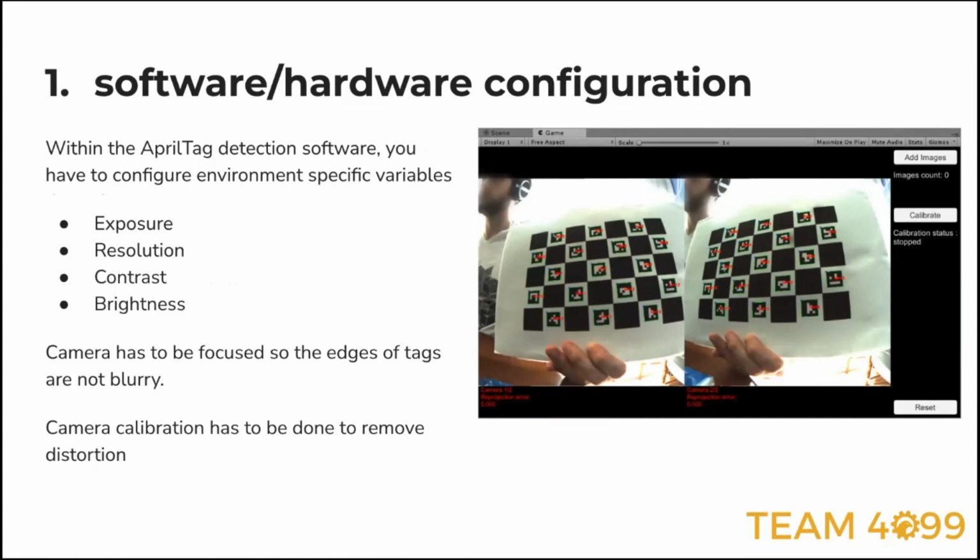And so the whole goal of camera calibration is to reduce your reprojection error, which is a measure of figuring out if light is coming to the camera, is my camera model accurately reprojecting that light back out to where it's supposed to be. So it tells you if your camera model is able to represent your camera in math properly.